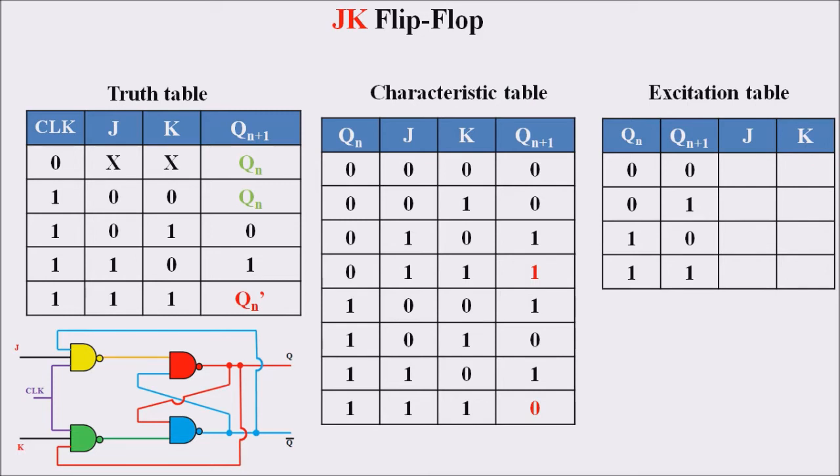So my dear students, now we are moving towards the excitation table. This excitation table is used in order to create the counters as well as conversion of different flip-flops. Thus, the output of all excitation tables will be the input value of that particular flip-flop. That is,